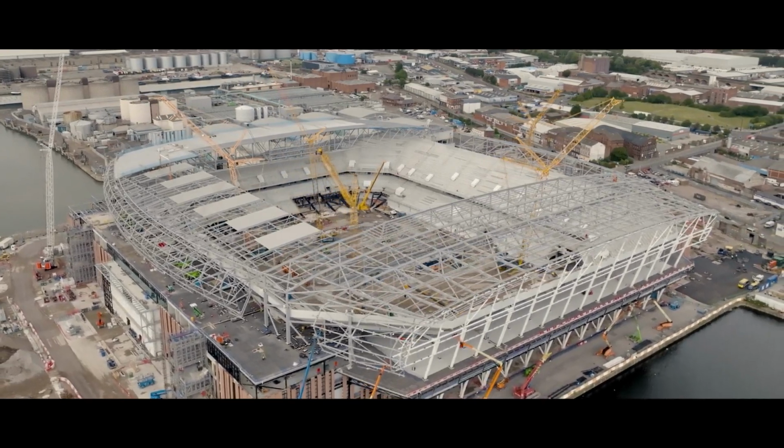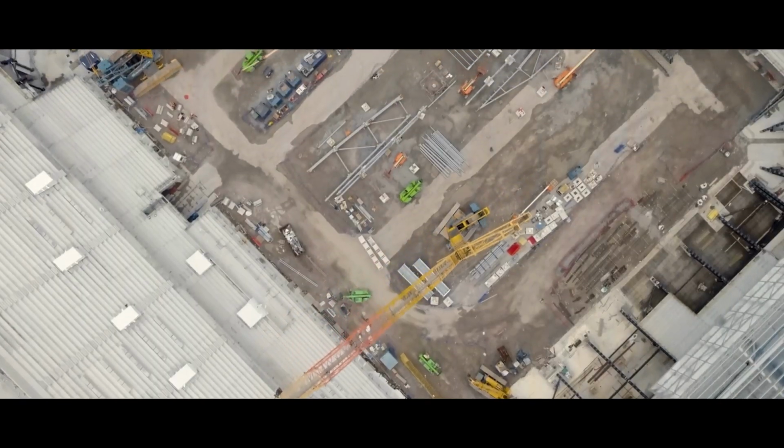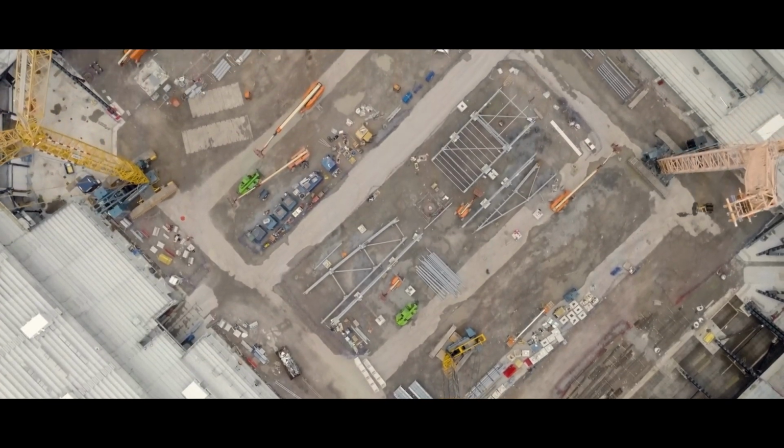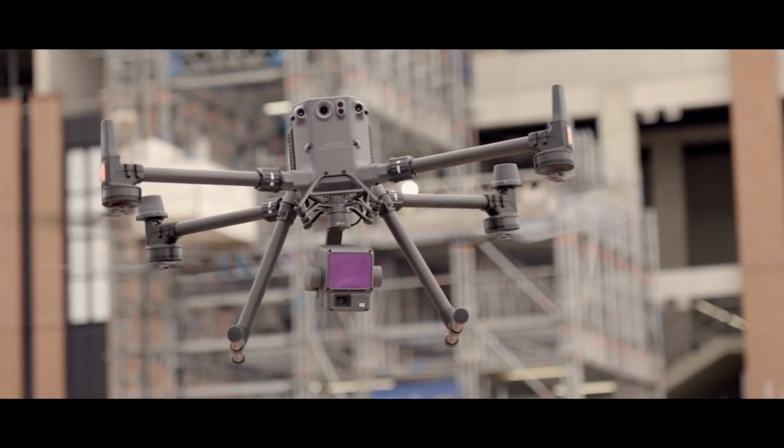There are some clear improvements in the data quality from the L1 to L2. The improvements of the sensor mean that you can fly faster for greater efficiency and collect more accurate data even when flying higher. It has better vegetation penetration because it now has 5 returns instead of 3, and it also has an improved RGB camera, which means that you can have greater efficiency when collecting photogrammetry and LiDAR data.